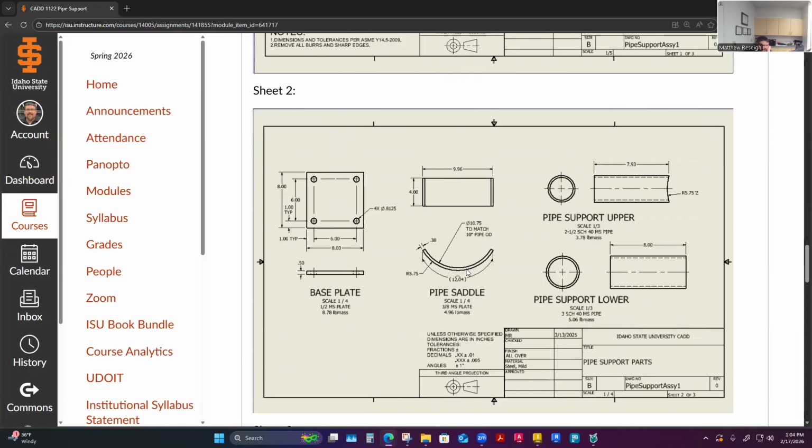A few people asked me about my dimensioning here. It's kind of worthless dimensioning in some ways. The material thickness is already 3/8, so this is not a super critical dimension to have. It's maybe a nice to know, but the material is driving the thickness. But I've got a couple radiuses called out, an outer radius and an inner radius, to match this. When this stuff gets formed partially like this, the technicians usually have some type of reference guide to judge if the radius matches.